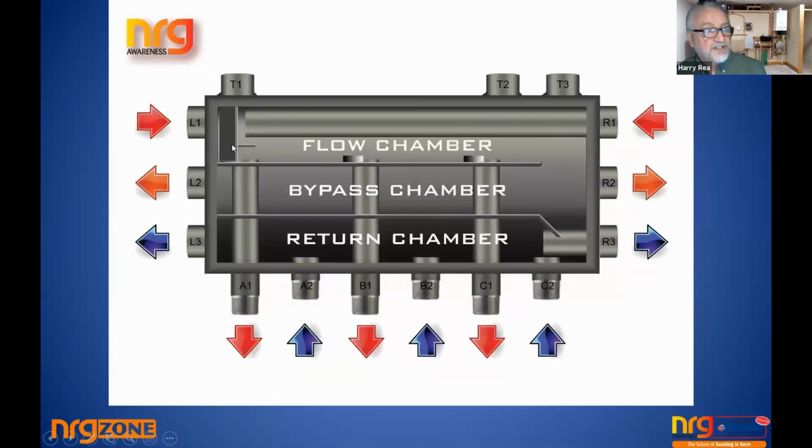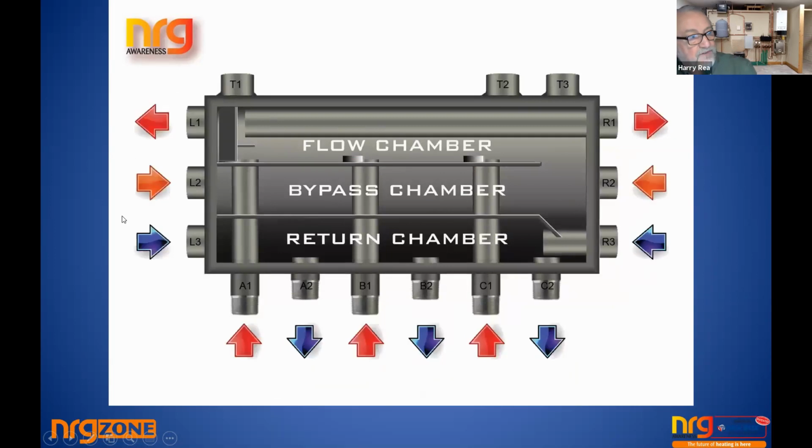So yes, I'm saying this is the flow chamber, and we refer to it as the flow chamber, and you can flow in from the left or the right, and you could feed back to a return from a boiler from here, because you are picking up the return, or here. But of course, this is the logical place, here or here, to take it back. But remember this, even though I've said that, you can watch the arrows, you can reverse everything.